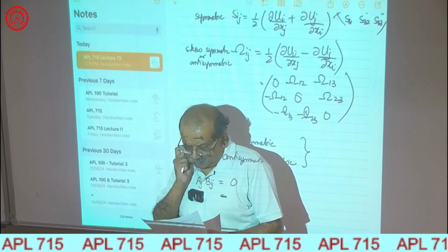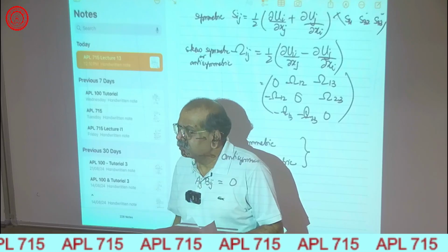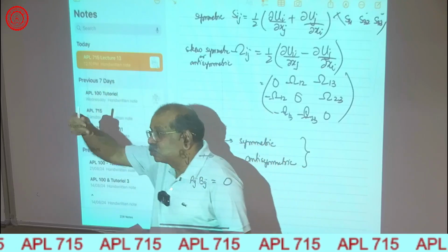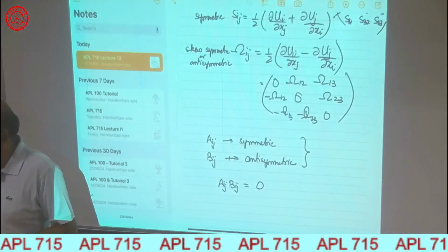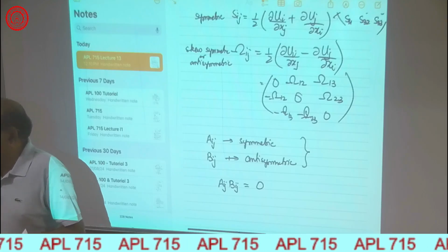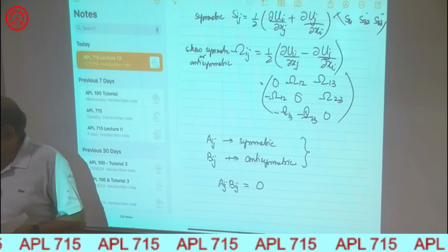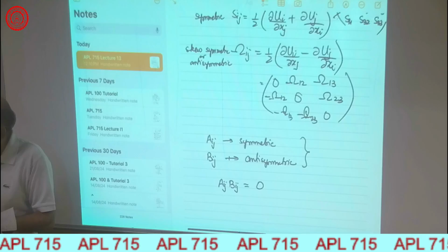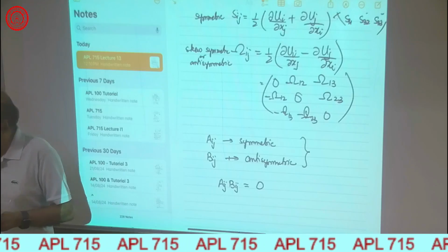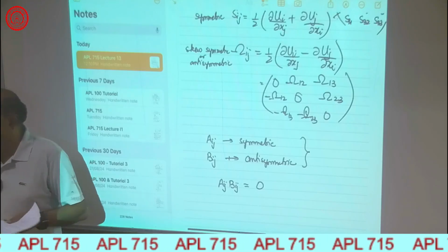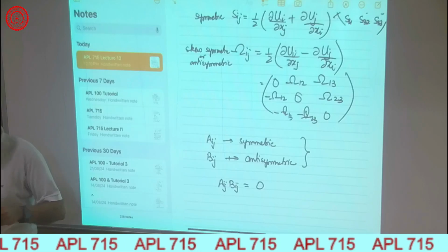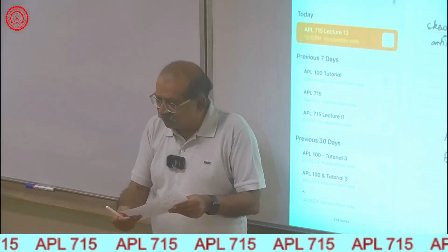This continuity equation, isn't it only applicable for the average of u_i? No, it's also applicable for the instantaneous. Because that's the continuity equation, that you start from. If density is constant, then you get two equations, mass balance and momentum balance. And the mass balance is partial u_i instantaneous by partial x_i is 0. So that comes from the continuity equation. And when you subtract the mean equation from the instantaneous equation, you get the fluctuating continuity.